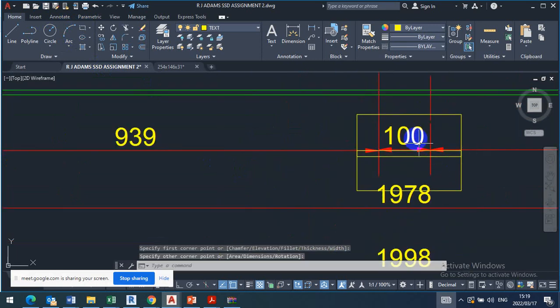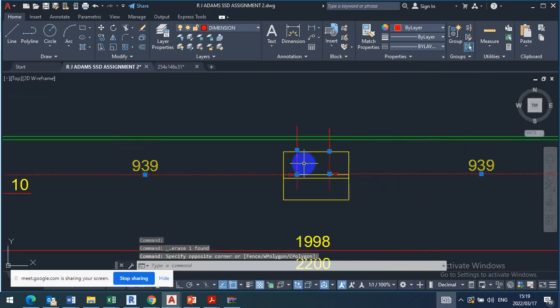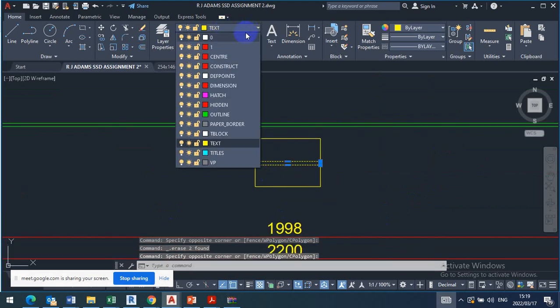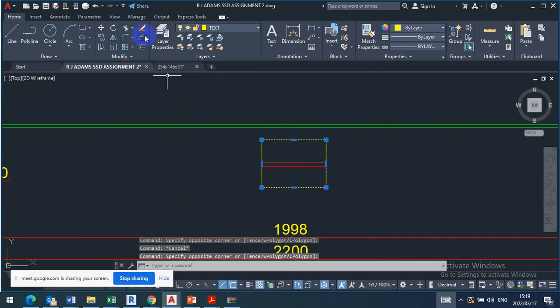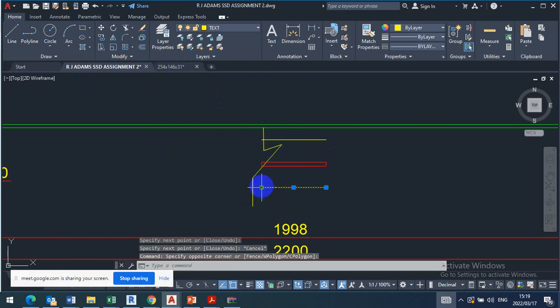Let's say like that. I'll delete this and delete that. From the top view, this will be in hidden details. Do you know that? Or bottom or top view, whichever you're looking from. Then here, it's supposed to be, let's explode, and then we cut. What the examiner wants is you to show like that, because it's just a piece. You come straight, you come in, you come out, something like that. Just showing us from the top that it's been cut from. Then trim.